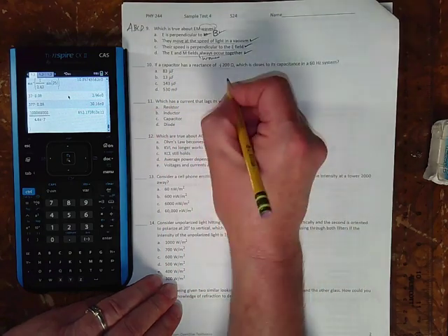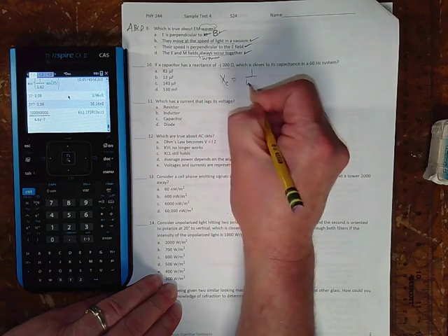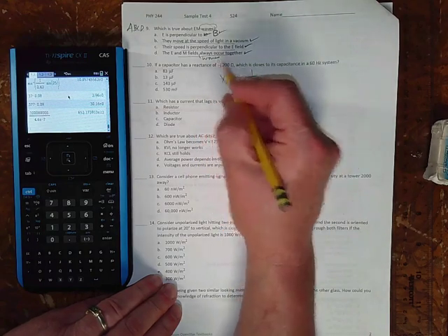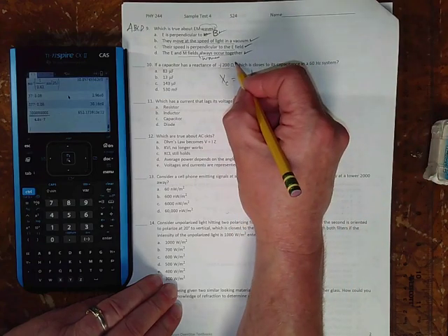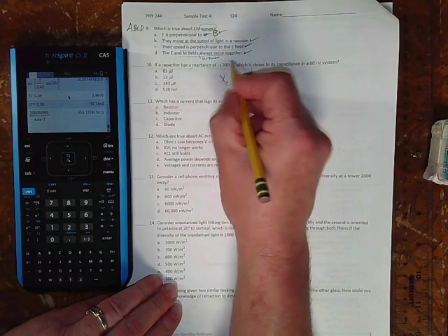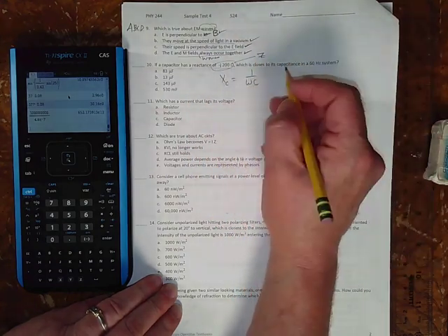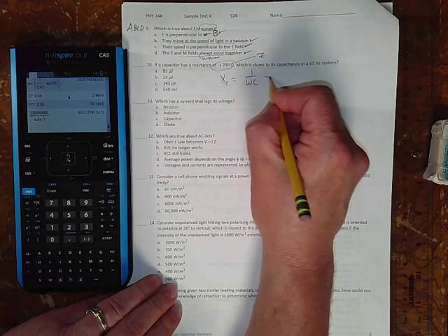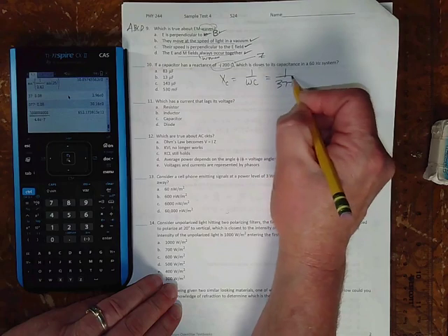All right, if a capacitor has a reactance of negative j200, what is the closest to the capacitance? So for a capacitor, X is 1 over omega C. The negative j is the coefficient that makes this a Z. Actually, this should probably be Z and not a reactance. So the reactance is the 200 part. And so 60 hertz system, so we have 377 for omega.